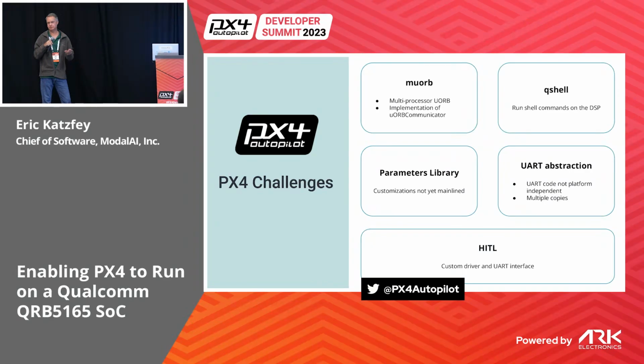The shell, you're probably used to using the PX4 shell. Well, now part of PX4 is running down on the DSP. How do you interact with that? QShell is basically a remote way to access the shell. There is no direct user interface, so you have to take shell commands and send them down to the DSP for it to run, and then the results come back. That's what the QShell module is. Another artifact of this split architecture is rethinking things like the shell.